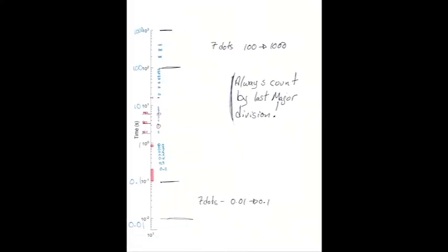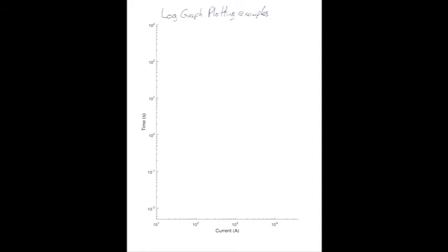So, let's get on to some examples. So let's start out with 2,000 amps for 1/10 of a second. So we're going to start out looking at amps. 10 to the 3, this is our 1,000, so we're going to count by thousands. 1,000, 2,000. So this is our vertical line that we're looking at, and we wanted 1/10 of a second. 0.1 is 1/10.